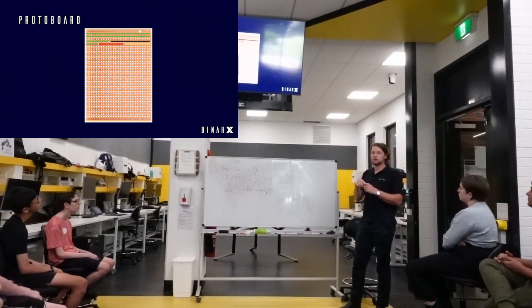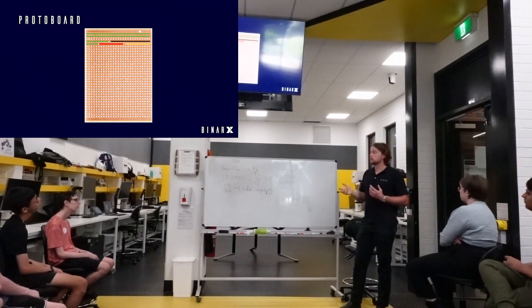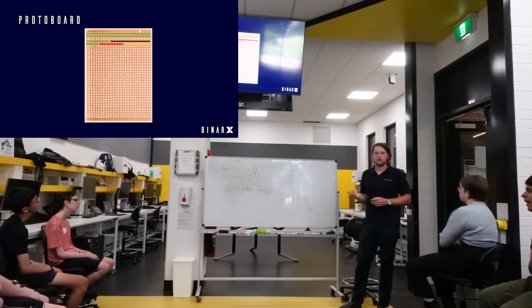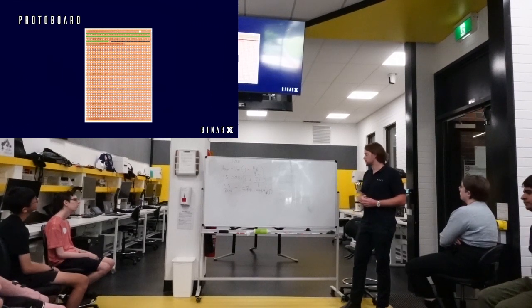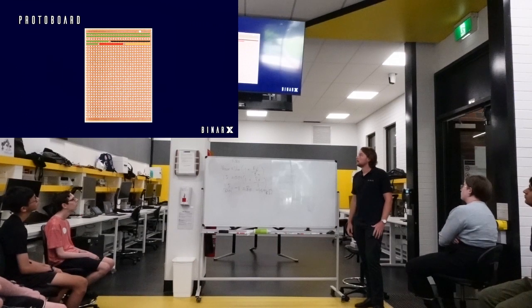So you can leave them connected wholly together and just use them individually for each component, or you can cut them with a scalpel and break the circuit so you can set it up how you want. These are more permanent options than a breadboard, because breadboards can have a lot of problems when you're running different electronic circuits. This is a more permanent option without going as far as designing a PCB, which is expensive to manufacture, and you can test your own things that way.